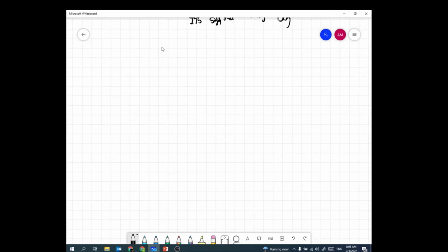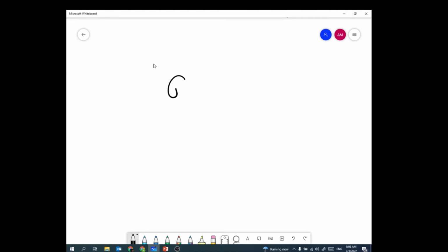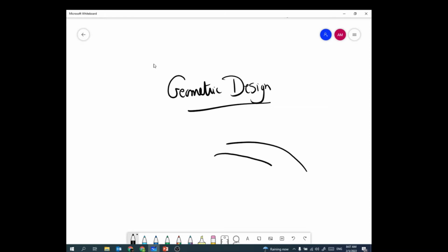So again, we're going to talk today about highway design. When we talk about geometric design, we care about everything related to this road that we drive on. The dimensions, when you look from this way, for example, the cross-section: how many lanes you're going to have, what is the width of the lane. You have a sidewalk, you have a shoulder, you have drainage, you have a curve, what's the radius of that curve so you can have a safe drive. You have an intersection, what are the different radii of this intersection's turns.